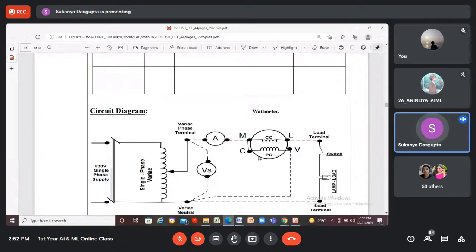And this type of wattmeters are basically electrodynamometer type wattmeters that we use in case of AC circuit. They are basically constructed with unity power factor because there are low power factor type wattmeters also in our lab. In experiment number 6, probably we will use low power factor type wattmeter for the open circuit and short circuit test of transformer. So mainly all the wattmeters are designed with unity power factor. So this is a type of wattmeter of electrodynamometer type whose power factor is unity.